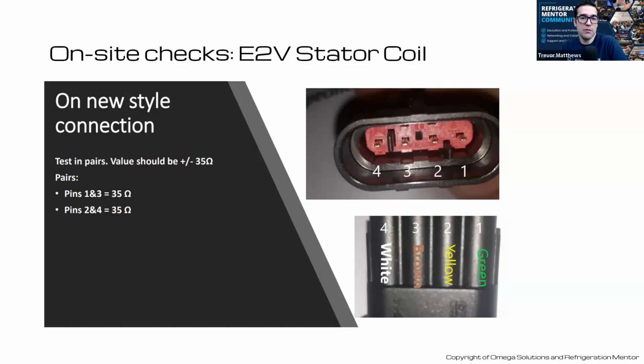One thing too, if you work in a supermarket, there are meat rooms and stuff, and they're spraying down everything, all the walls, and water splashing up can affect either the transducers or the electronic valve cable. One contractor about 8 or 9 years ago said, Trevor, we use heat shrink. So all their electronic valves in the wet, moist areas, they pull a big piece of heat shrink over it, so any water that gets onto it doesn't really get into the valve itself. It reduces some rusting and things like that. Yeah, stops the ingress.